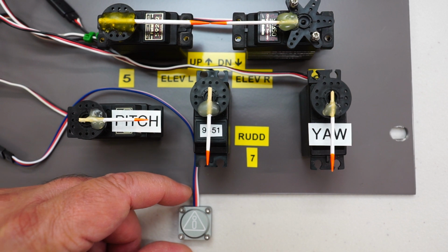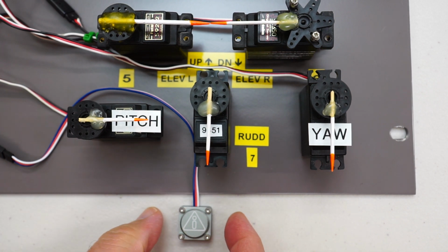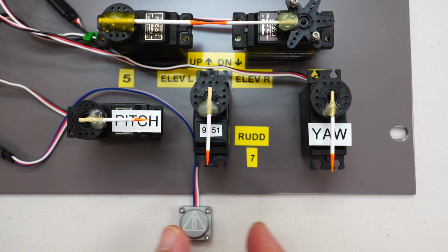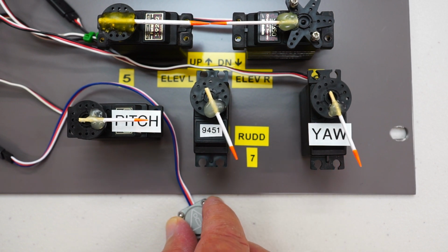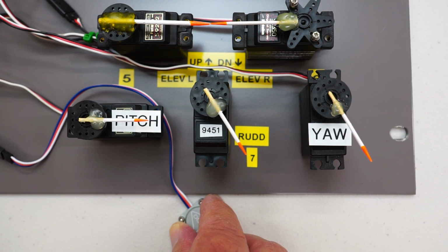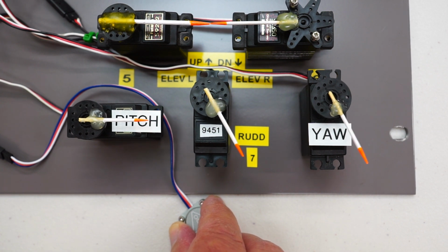If I move the gyro, so let's move the gyro in an anti-clockwise rotation. I'm going to rotate it anti-clockwise in that direction. So these two servos should move off to the right. Let's try that. I'll try and do it as smoothly as possible. So they're moving in the correct sense. They're correcting my anti-clockwise movement.